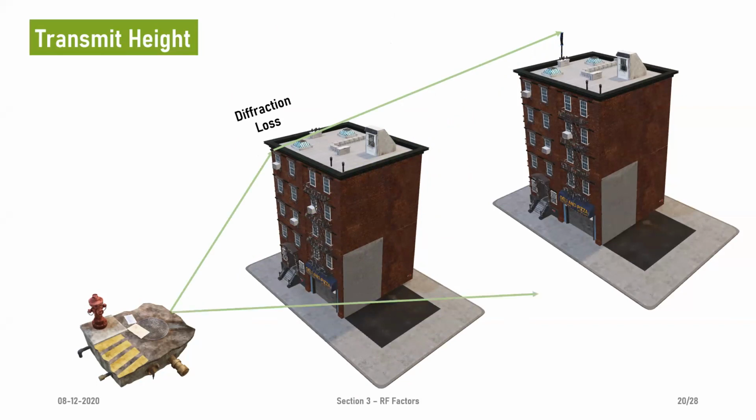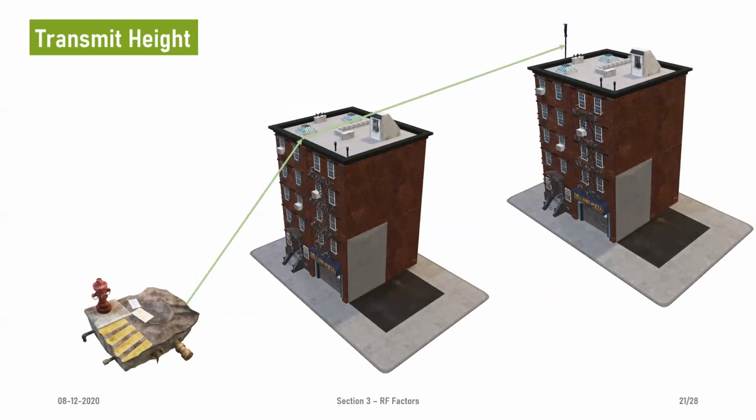One thing I want to point out is the multipath propagation known in wireless communication. The signals would not just diffract, they will also refract and reflect from different obstacles and then reach the gateway. The gateway superimposes all those different attenuated and time-delayed versions of the signals. But that is not the topic I want to consider. Note that the diffracted signal is mostly considered to have the highest signal strength. So assuming a manhole monitoring sensor incurs some diffraction loss reaching the gateway, at the same point on Earth, a street light controller is going to incur some attenuation and then reach the gateway. This diffraction loss is necessarily different when comparing the manhole monitoring sensor and the street light controller.